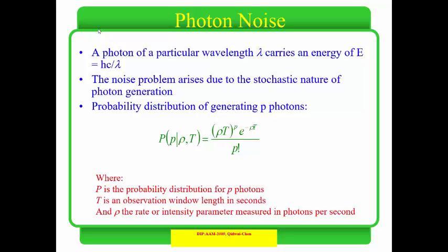If we start with the photon noise, when we have incident light on this sensor, the number of liberated electrons is not fixed. We have a certain probabilistic distribution of this photon. Maybe I am configuring my system, saying that if I have this type of intensity, I will have this value of current. But this is not always the case. This current will be generated with plus or minus error. I will not have this exact number of electrons created. So here I have a certain probabilistic function of this form.